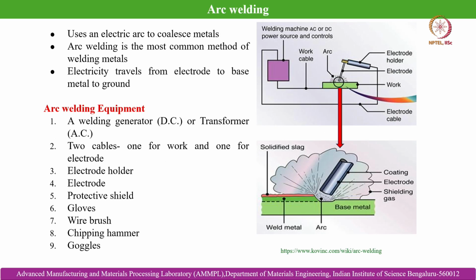So, the next in line is arc welding. Yes, of course, it is one of the most versatile welding techniques. I have already discussed with you in one of the earlier classes the basic principles, how we generate an arc, that is because of the release of electrons from the negative electrode, which are transported towards the positive electrode, that means the anode, that means the workpiece, and thereby the arc is generated.